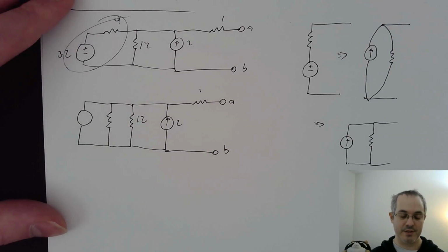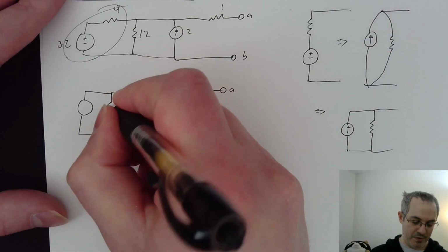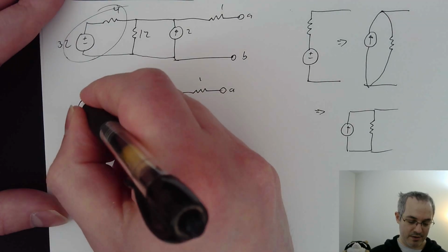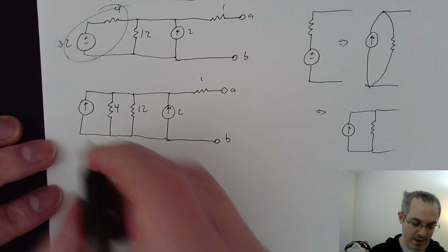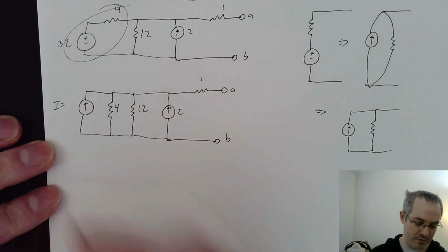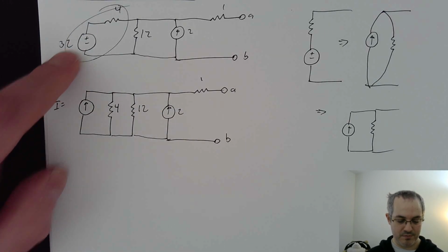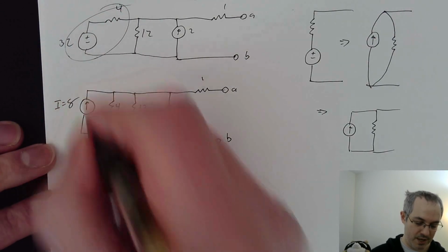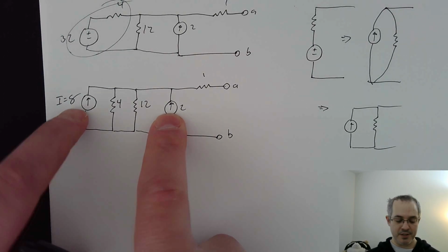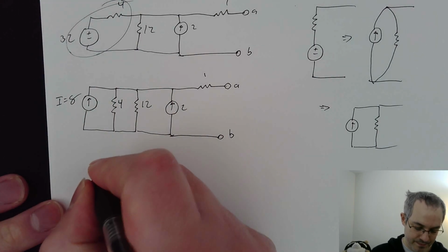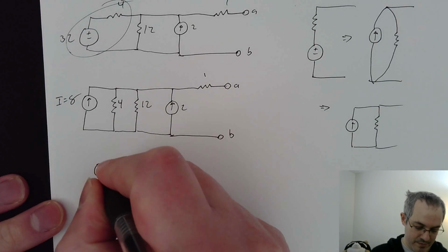And that's what we'll see in this case. Remember, the resistor stays the same, and it's going to be up because it's minus plus. Oh, and the current value, the source for that, will be 32 divided by 4, 8. These two current sources, they're facing the same direction, so they add up. And they're parallel. So that's a 10 now.